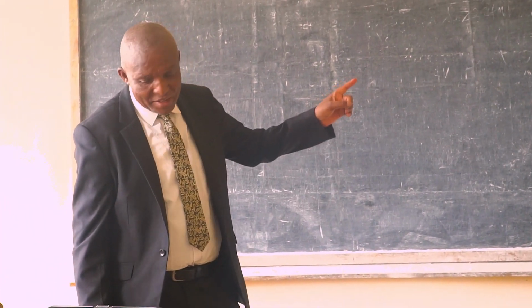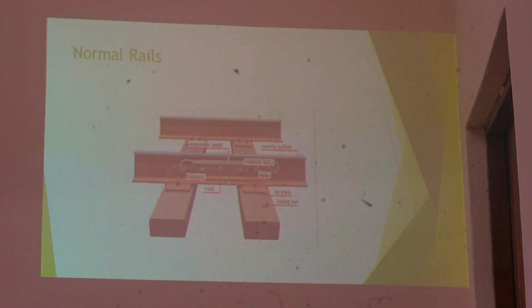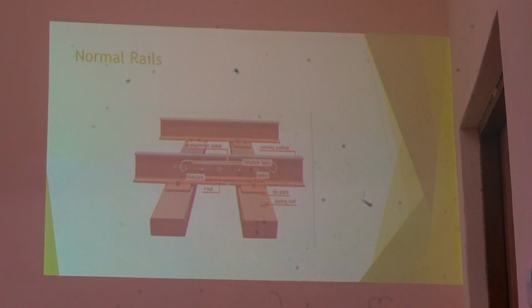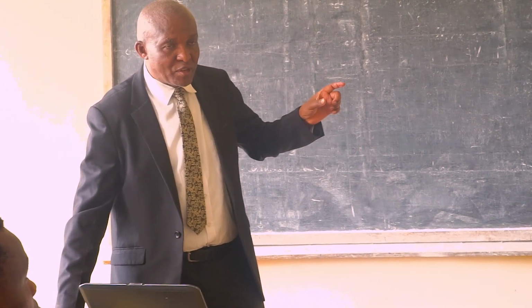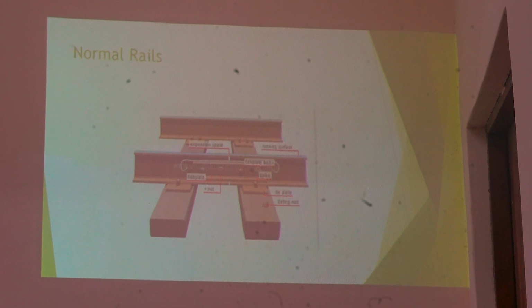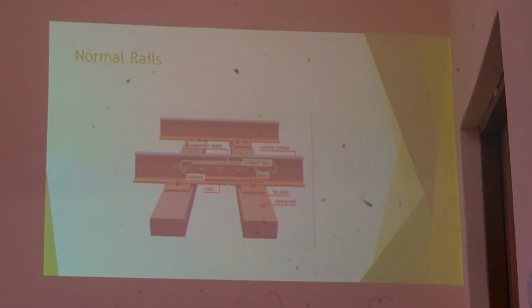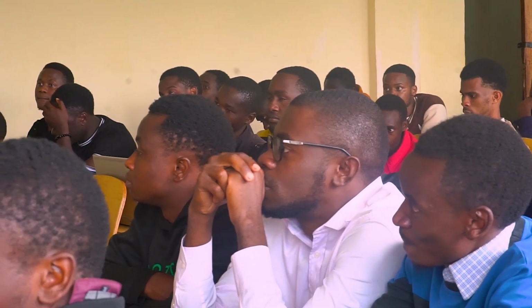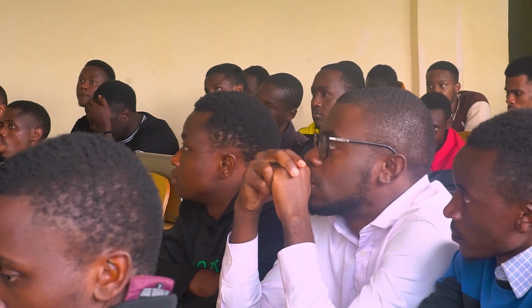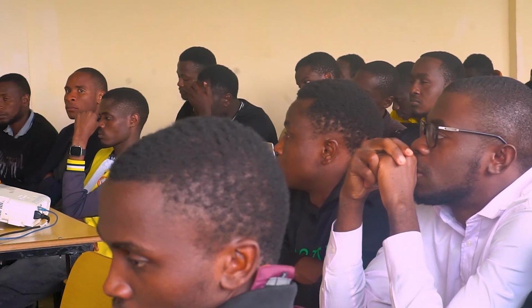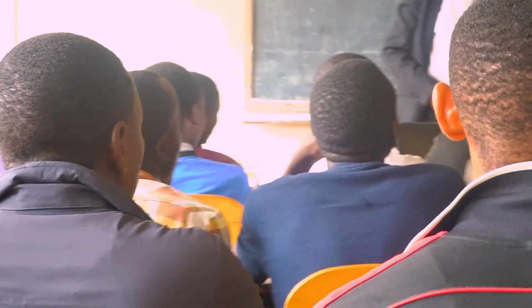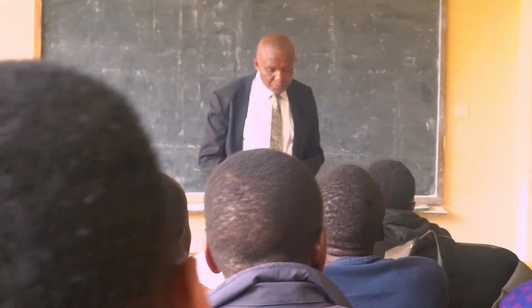You can see the fish plate there. I don't know if you can see, I try to show it here. Pieces of a plate which is connected with rails. And normally you can see it's connected with bolts. Normally the bolts are fixed: one bolt is directed in this direction, the other bolt is directed in the opposite direction, so that when there is derailment, say a train fails, that plate will not be removed, and then you will have a serious accident. So they use what we call fish plates.